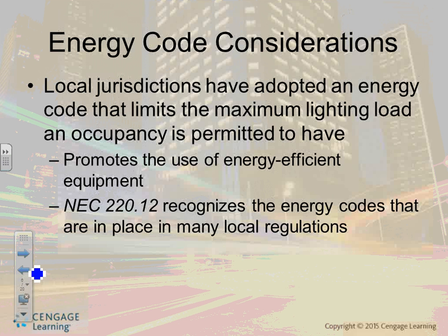You have two options of feeding the addition, right? Either existing panel, pull branch circuit to the 10,000, not a good idea though. Or pull in a feeder or two to that area, and feed that area separately from its own separate panel. And that's what most of the people do.